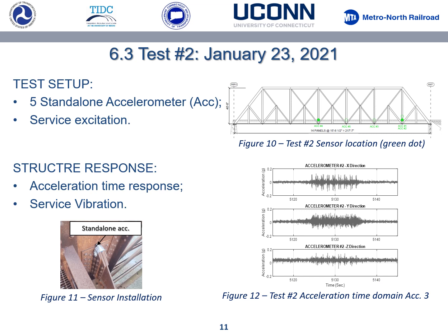The good thing about these accelerometers is that there's no data acquisition system and no wire, and the big disadvantage is that it's hard to do the synchronization. So we need to read each accelerometer individually. As you can see in figure 12, that's a reading from accelerometer 3 from one train passing over the bridge. Right now, we're still processing this data.